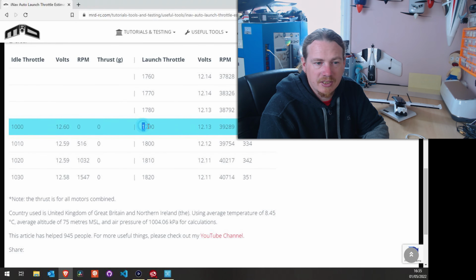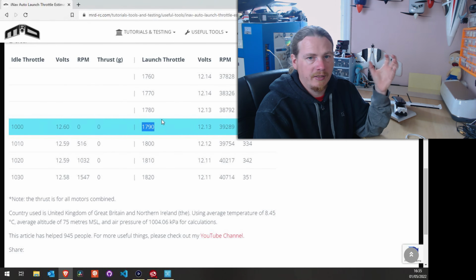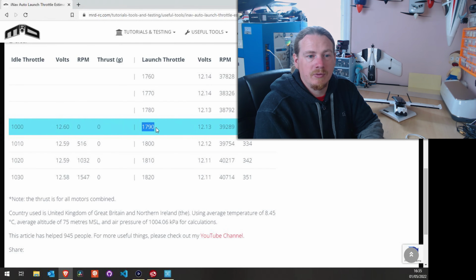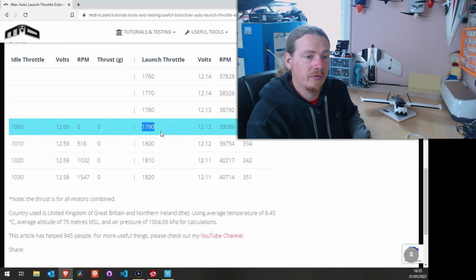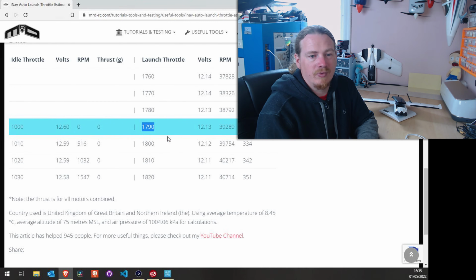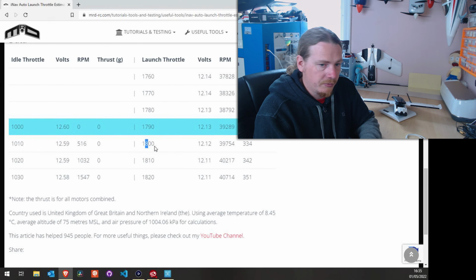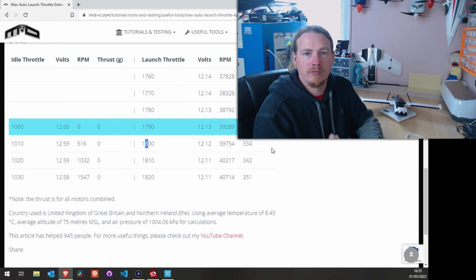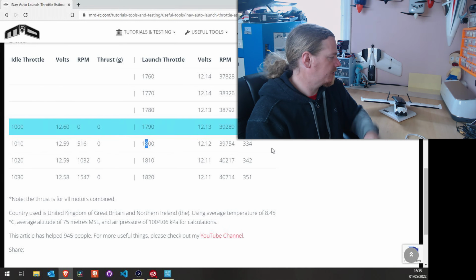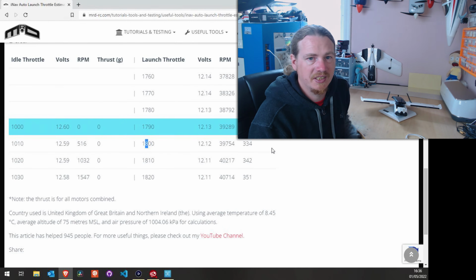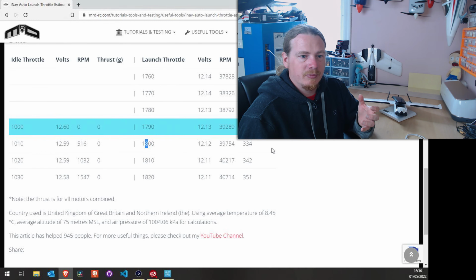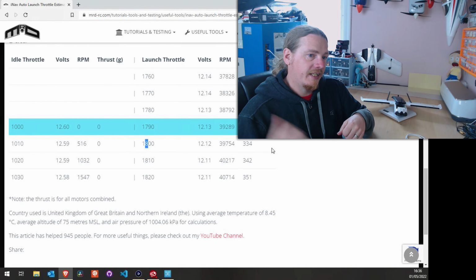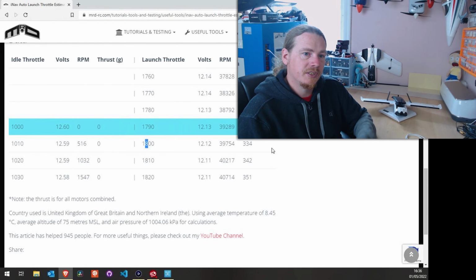So it's slightly lower on this model than what I've got it set to. But to be honest, this actually goes like stink, so I probably could lower it to that. Or maybe round it up to the 1800, which will give me a little bit of leeway if I'm going for maybe a second flight on this pack, because that pack will last 25 minutes easy with fun flying. So this is a pretty good estimate. With my AR wing, it actually overestimated and I reduced it slightly.